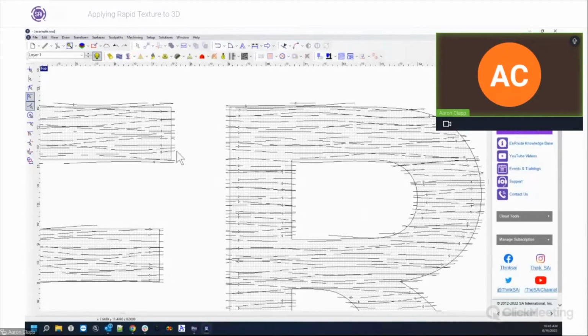So that's just something to be aware of. It does this so that you can complete the cut properly, so that it always goes at least to the edge. Because if it went half the diameter in, you'd always have incomplete cuts. And so it always extends the line a little bit past so that it makes sure and cuts the edge.